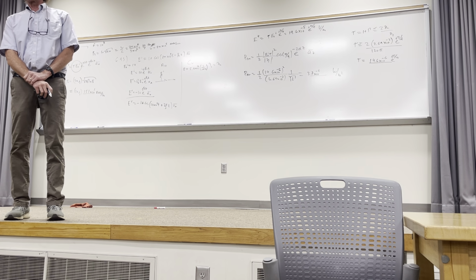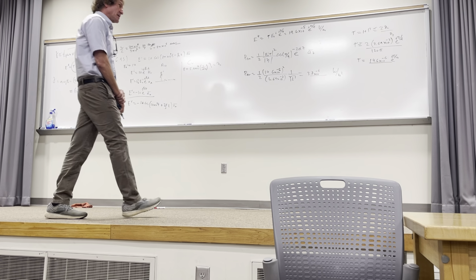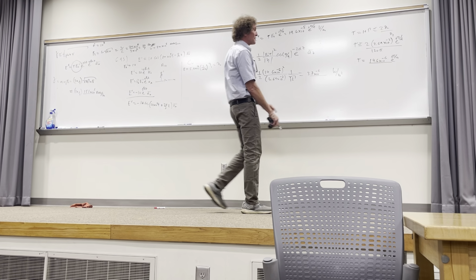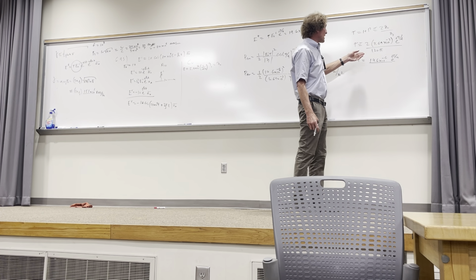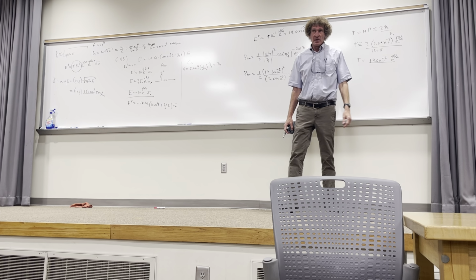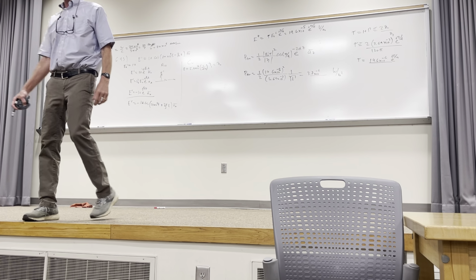But I want to tell you, the orders of magnitude of difference in the actual values of the intrinsic impedance need to be considered carefully, because here, if you do 1 plus the reflection coefficient, well, the reflection coefficient is about -1, you get 0, right? So you have to use the other form of that, which is 2 times eta 2 over eta 2 plus eta 1. You can ignore eta 2 in the bottom. That's the way it's done.